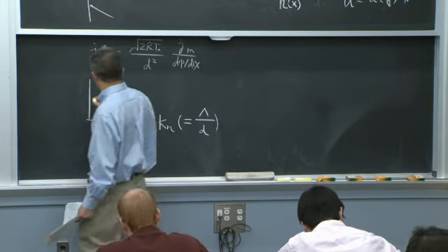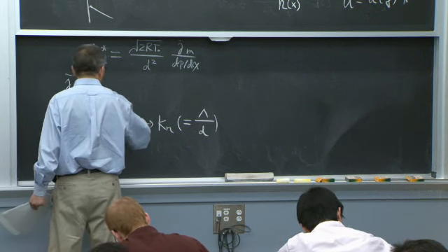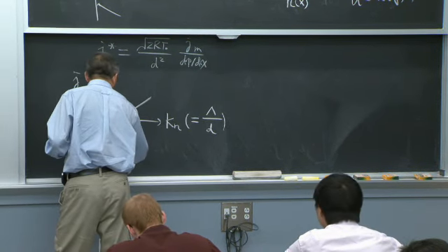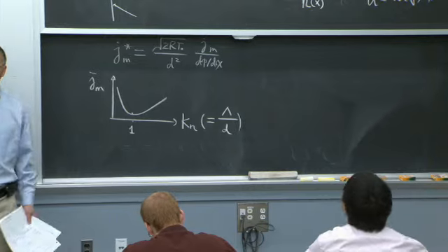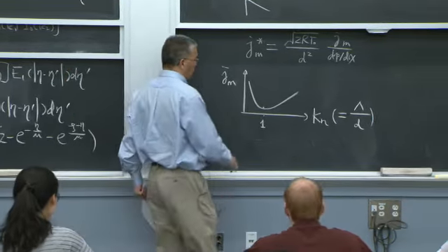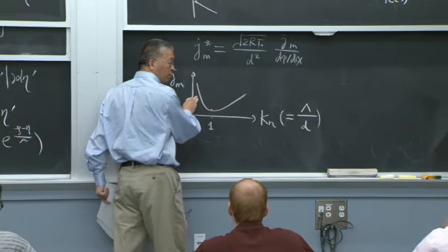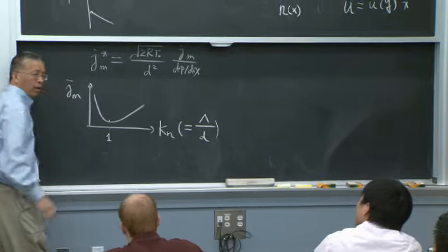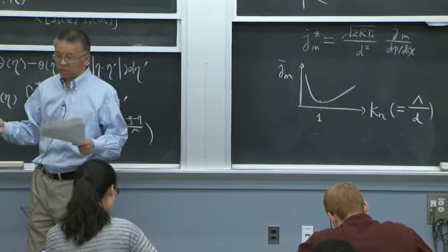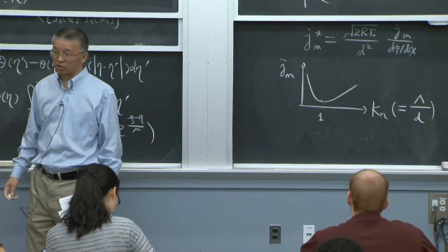Okay, so what they found experimentally is that it goes this way. This happens around a Knudsen number of 1. Here, at very small Knudsen number, that's the continuum. At very large Knudsen number, that's rarefied gas flow. And in between, there is a minimum. This minimum is called the Knudsen minimum. This was found experimentally.